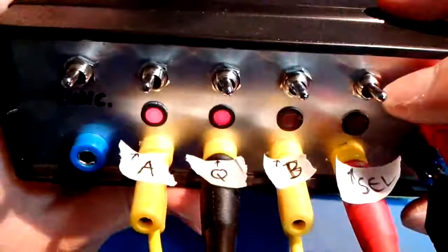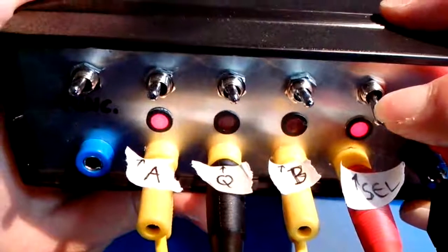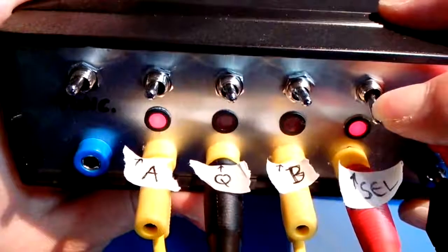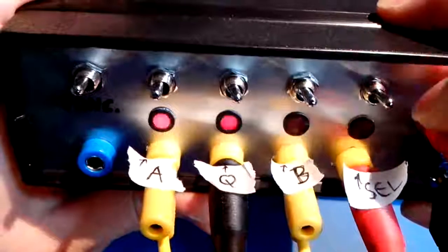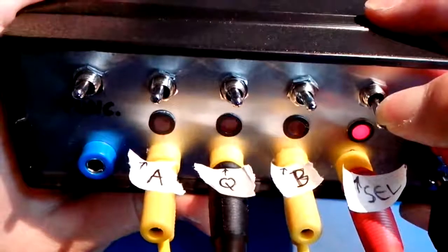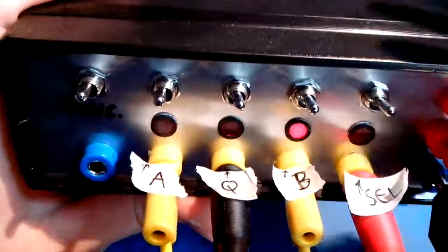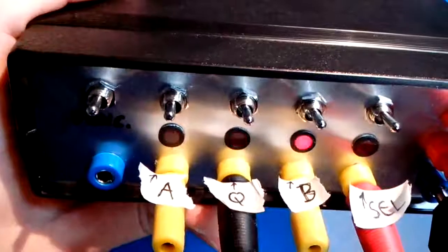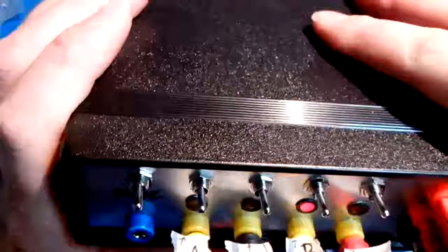Now if you toggle the select input from 0 to 1, you can see that the output Q will start following input B. Release it again, output Q follows input A, right? So that's basically how it works. And if you implement this 16 times in parallel, you can choose between 2 16-bit values instead of 2 1-bit values. So that's all basically.